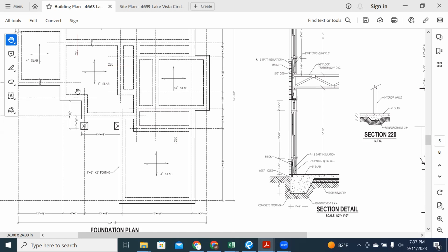This is after the plumbing is done, by the way, right? We talked about the plumbing. Then they're going to dump all the gravel all over to cover everything, give it reinforcement. And then they're going to come and put this right here, this rigid insulation. It goes on top of the gravel. It's a piece of plastic. If you saw the video, it's a white plastic that we put down.